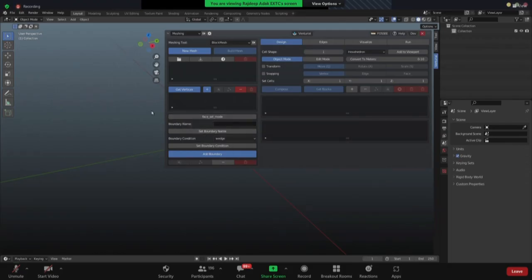The section over here, as you can see, is related to boundaries. So this is where you add your information about boundaries. Then finally, you have this section over here. This is where you add the information about different blocks of your geometry. For a simple cavity flow, there is a single block and a simple 8-vertex cube. So essentially, you add that information over here. And this is all there is, as of now, which is of importance just for the example that we're going to run through.